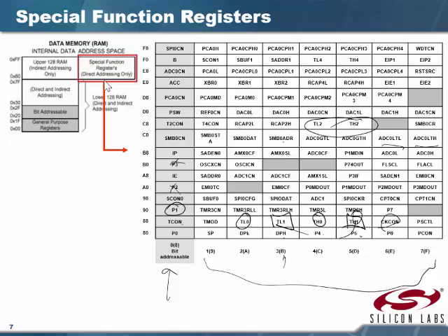One that we talked about earlier, in my very first demo program, is this one here in the upper right-hand corner. That's our watchdog timer control register. That's how we turn off the watchdog timer. We also probably have some bits there where we can turn it on and tell it how many clock cycles before it times out. So that's our watchdog timer register.